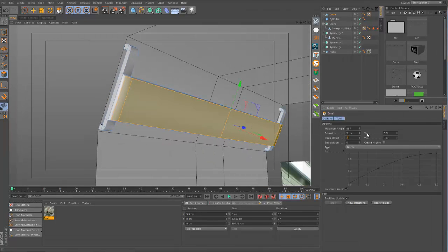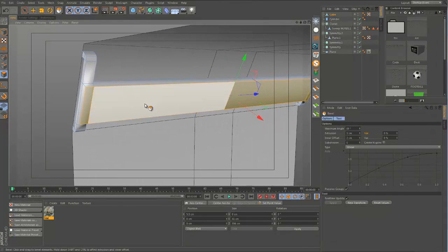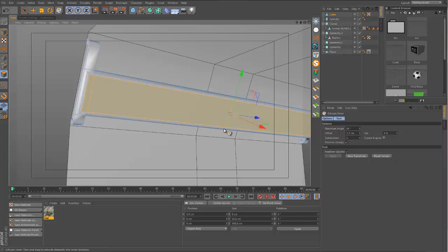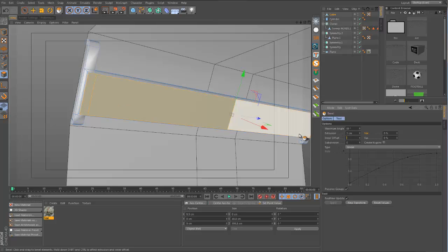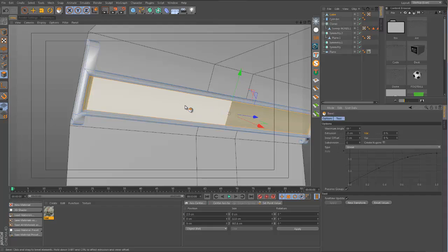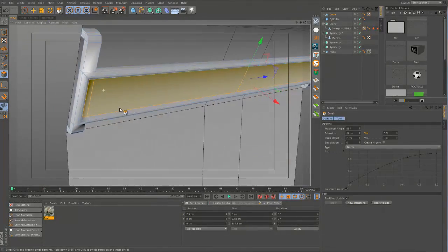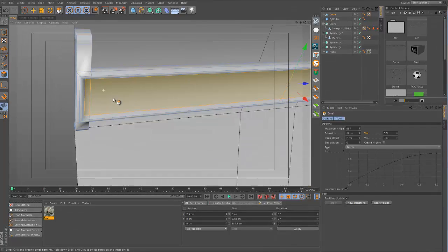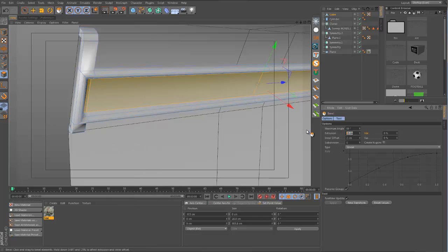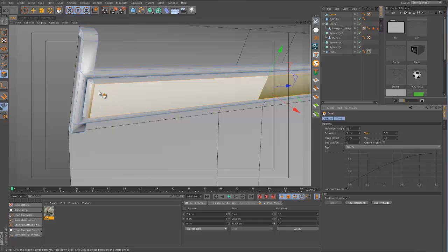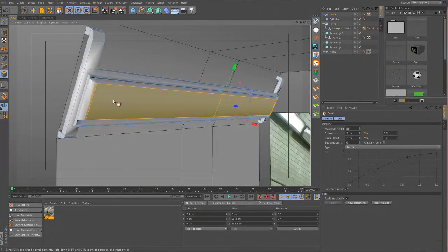Inner offset, let's make it 2, so it's more slanted. We are going to extrude inner, so let's bring that in. Let's bevel, extrusion 3, inner offset -2 this time. Oops, no, we want 2. Nope, it's the extrusion which should be -3. Excuse me, I'm getting a little confused here. So that's gonna go back in again like this. And then we'll bevel one more time, new transform, set the extrusion to 5 this time. So this is gonna stick out quite a lot. So this is like the frame and this is like the light bulb.